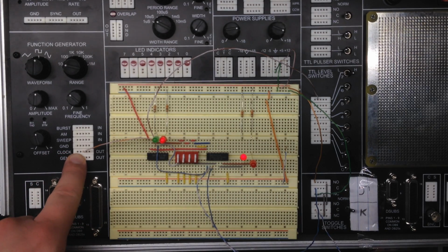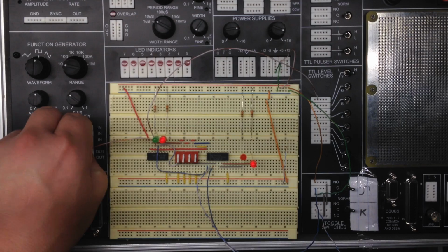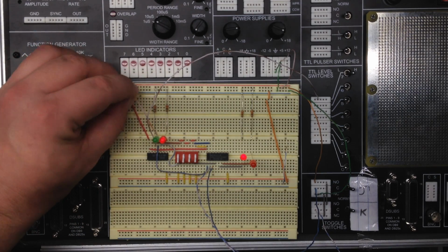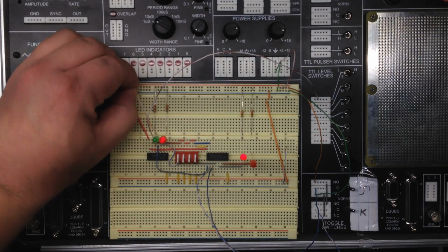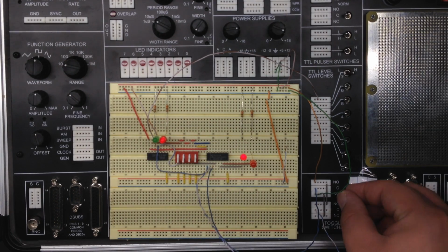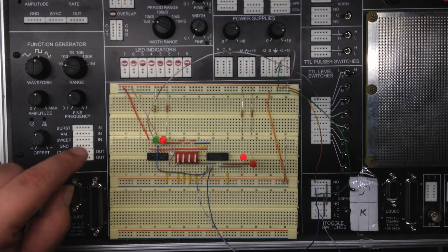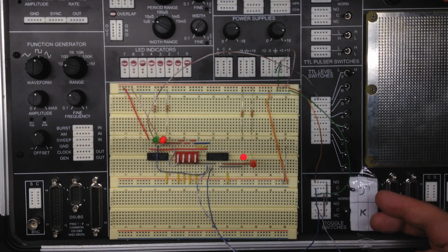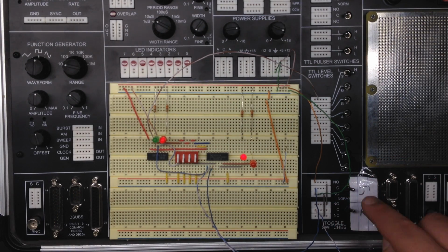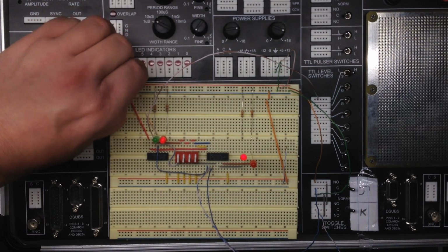So we're going to take the clock, and we're going to show the toggle happening to show that we do have the clock. And then we're going to plug our clock into a constant high on the breadboard. And we see that we have no change, that the state does not change based off of the switch because we have a constant high on our clock. We'll leave both J and K set to high so that when we go back to our clock, we'll be able to see the toggling happening, showing us that our clock is active.